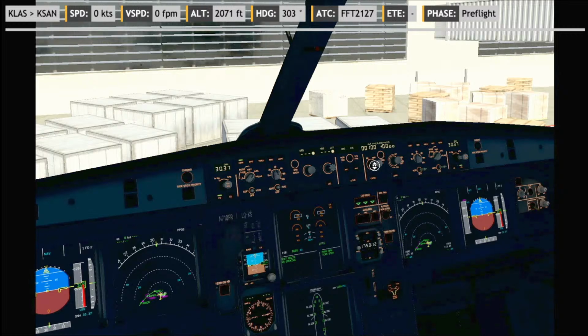Top altitude flight level 190. So we'll select that. If you want to know, I was looking at my standard instrument departure plate there, which gave me the exact altitude I should set up here. Normally ATC gives you this, but since we don't have any air traffic control here, we have to do it ourselves. And vertical speed dashes as well.